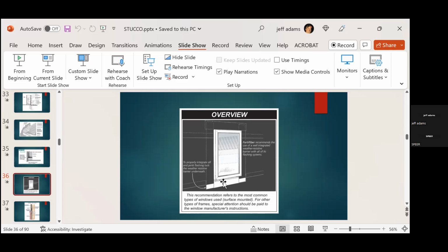They said, well, it gets plugged up with stucco and doesn't drain. I call BS, just for the fact that these products stay open to the atmosphere so much that these plastic Fortiflash sill flashings here get all wrinkled up and shrink and everything like that. And so they're very much wrinkled and crinkled up to create drainage channels in these products. I do like this detail, but keep in mind it does not necessarily coincide with the code, because the code does say that these sill flashings must terminate between the layers of WRB.